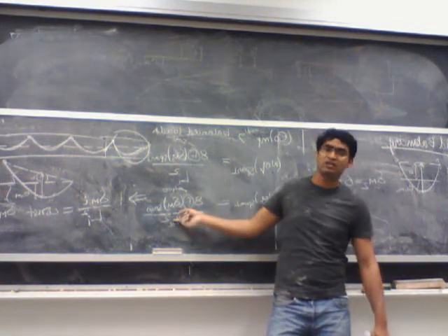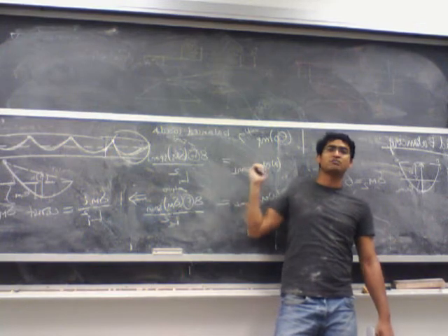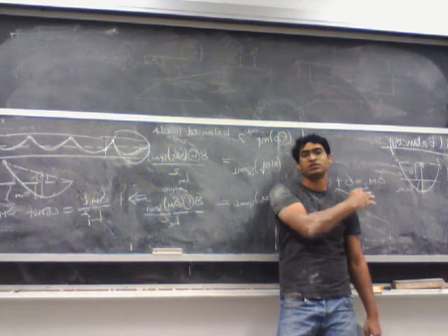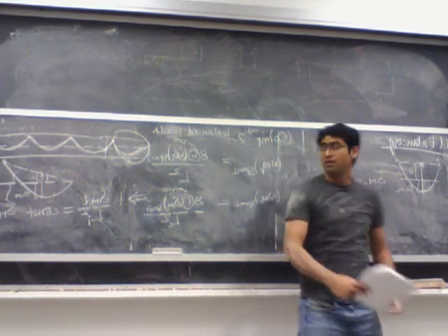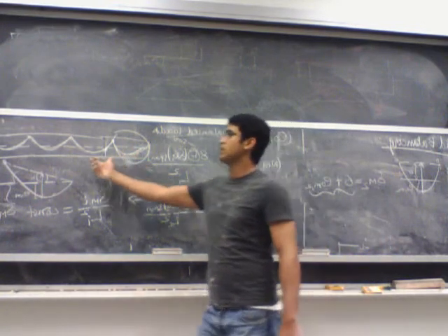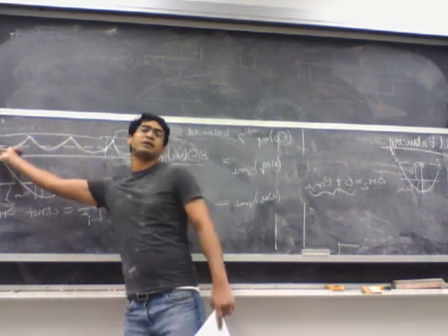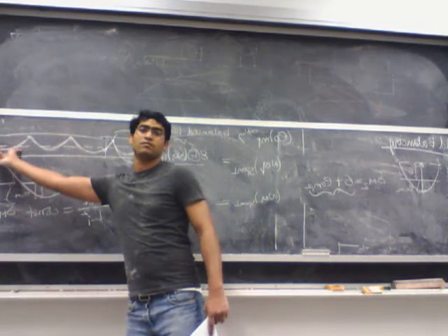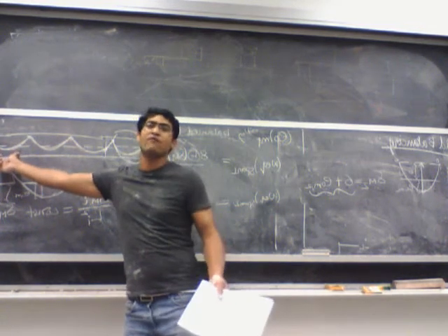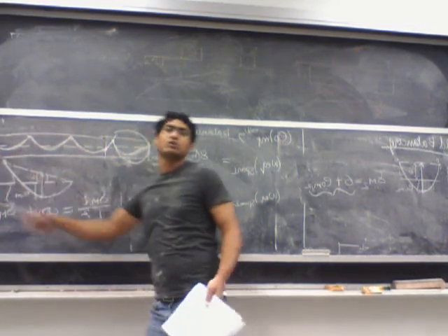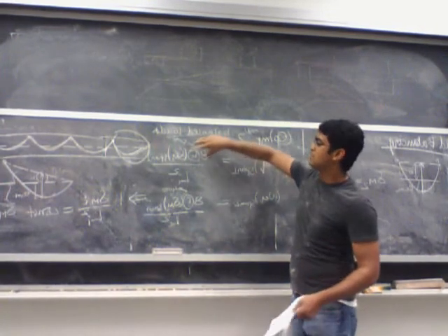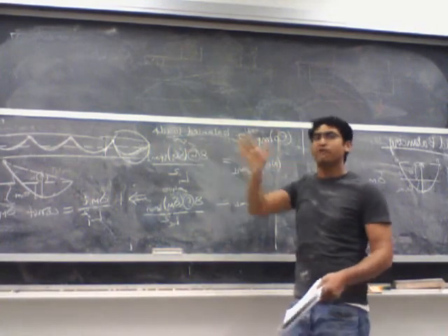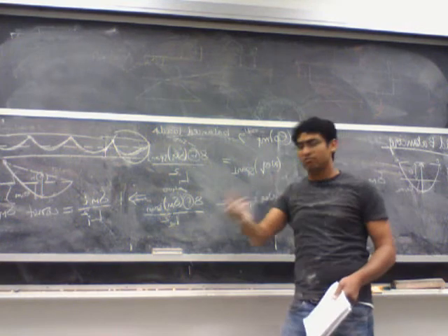The span can change. The equivalent load which is balanced on each of the spans can also change. It can say, okay, balance 90% of the dead load on this one, 80% on this, 80% on this, and 90% on this one. Which will be pretty weird, but you can have a different omega equivalent also. So just to be safe, it's always easier if you just calculate the F for each one of the spans and pick the larger one.